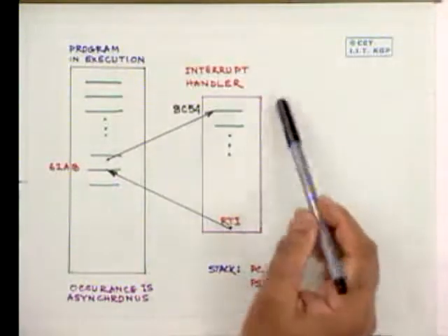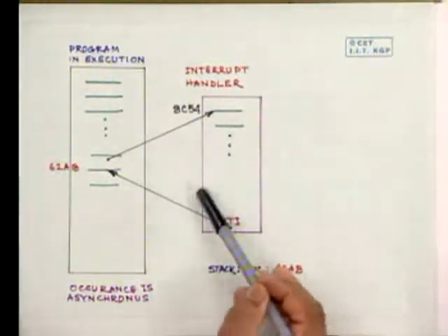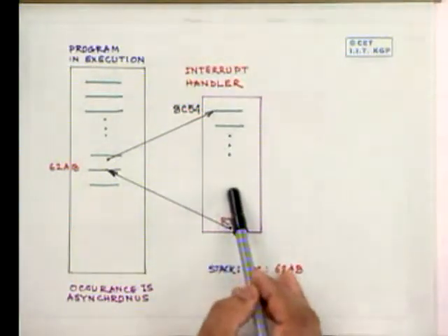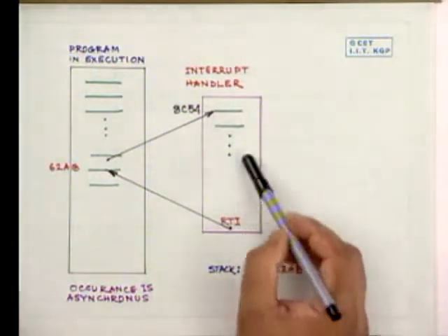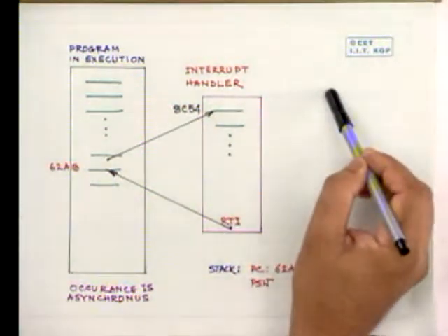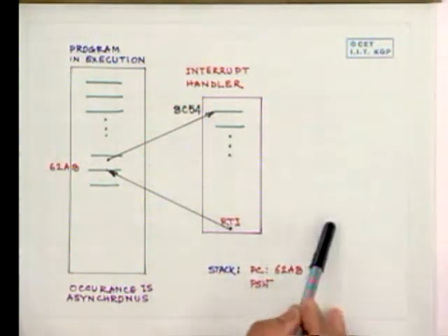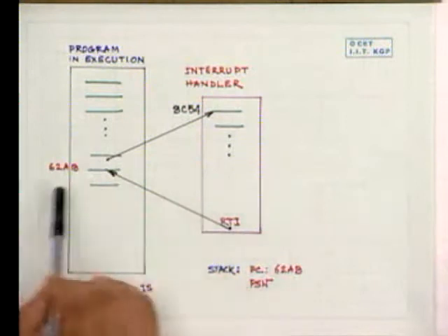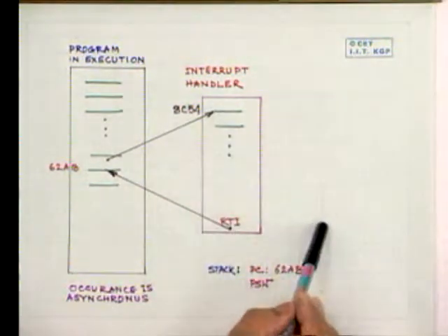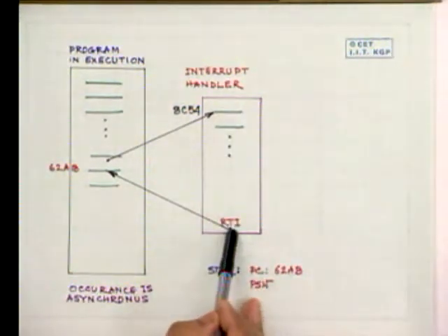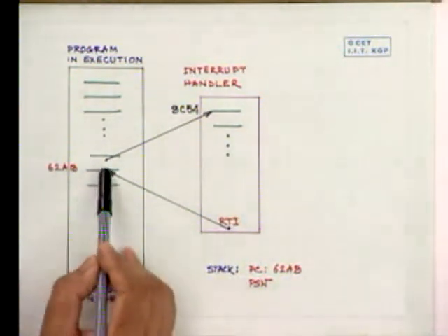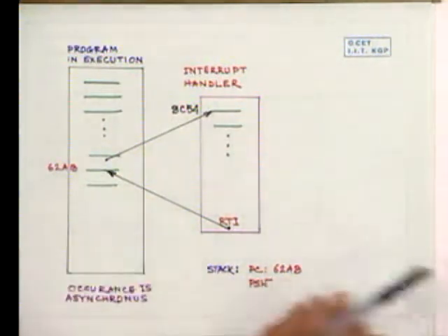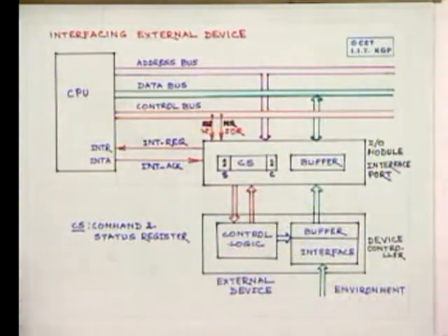Now we'll see later on situations where there can be an interrupt within an interrupt when more than one device is there. Let me tell you that in that case, if there is an interrupt within an interrupt, it will go to another interrupt handler, execute that interrupt, and possibly come back over to here once more at the end of that interrupt. Then this portion will be executed and the control comes back over to the original point of break. Right.